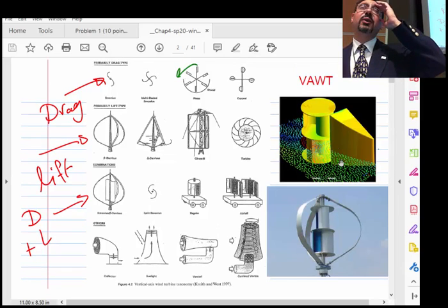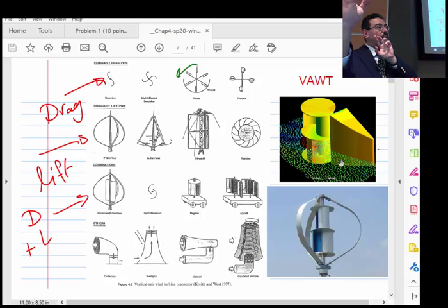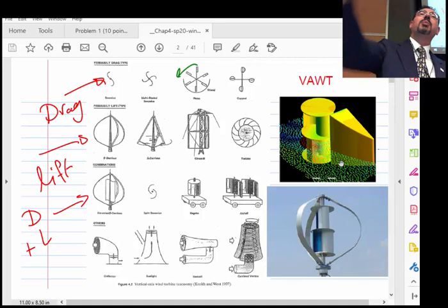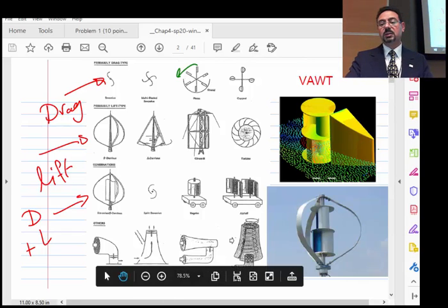There's also a professor, I forgot, it was Arizona or Nevada. He got a lot of money by basically suggesting those vertical axis wind turbines, when the flow leaves them and the flow is spinning in this way, maybe we need to put another wind turbine downstream, rotating the other way. And so you leave this guy rotating this way, you will push the other one the other way, and that improves the efficiency of the second one. So it was about how you stagger or rearrange the farm so that the performance is improved because of the wake coming from one to the other.